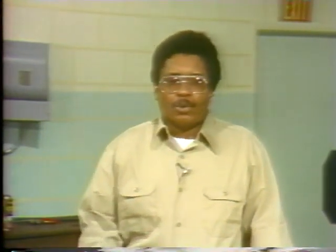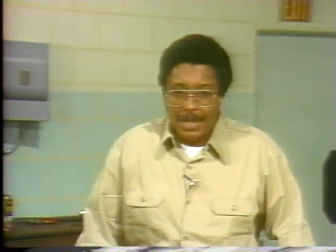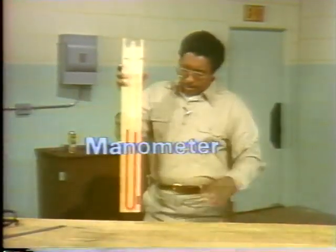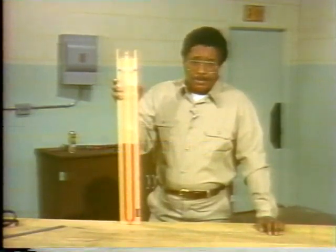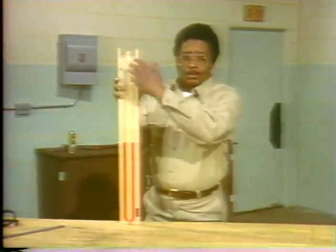In this segment, we want to show you how some of the most common pressure measuring instruments work and the types of measurements you can get from them. Let's begin by discussing one of the simplest devices for measuring pressure, the manometer. A simple manometer is nothing more than a U-shaped tube that contains a fluid and is open at both ends.